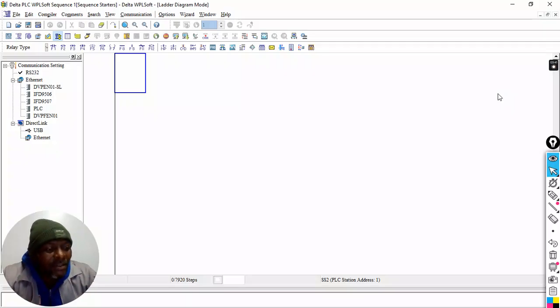But if it said only after 10 seconds, motor 2 starts, then it would have been an automatic move. It would have just required a timer. After 10 seconds, the other one kicks in. But here it says only after 10 seconds, motor 2 can start. All right. After 10 seconds, motor 1 stops. But motor 1 can be stopped by us. But if we don't stop it, after 10 seconds, motor 1 should stop. After a further 10 seconds, a stop button, an emergency stop, or overload should cut the circuit immediately.